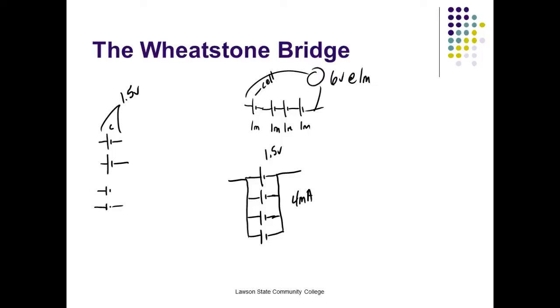And that's exactly what they do when they build these big old solar panels. They're rated at a certain voltage using a certain amount of light at a certain current. And how do they get that? Well, they build the voltage up by hooking the cells up in series, and then they hook them in parallel to get current. By the way, battery means a group of.